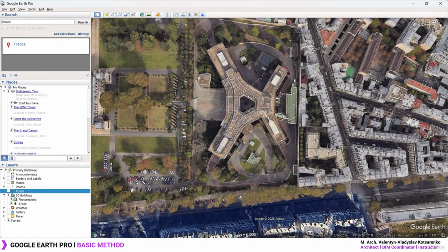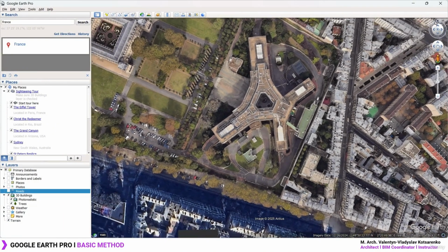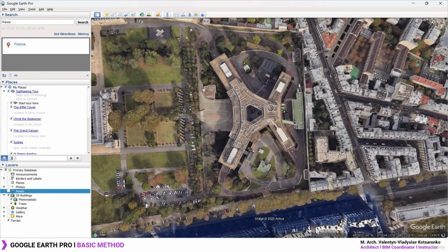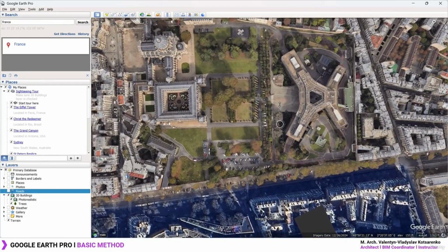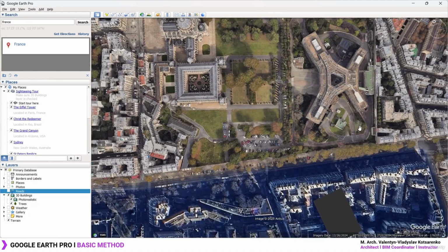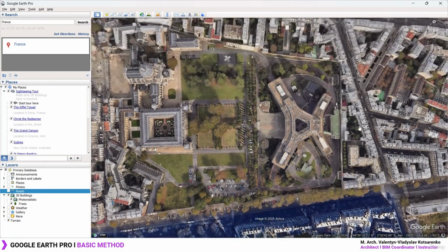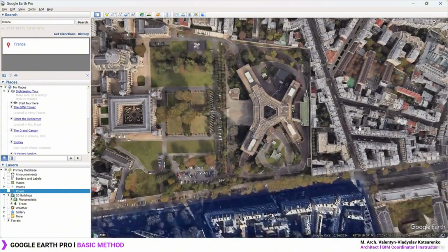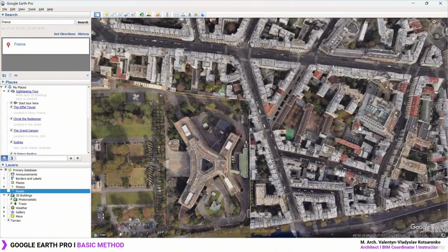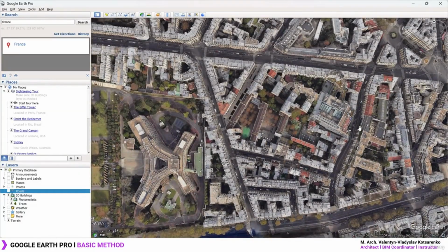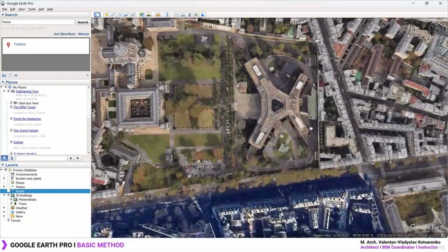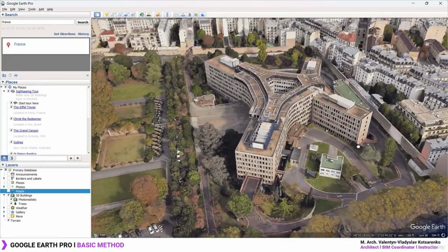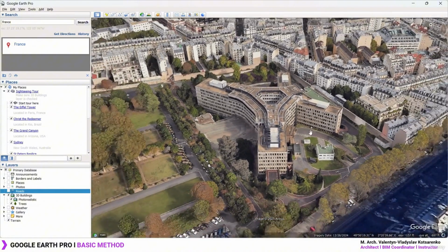Now you can do the fly-through with the drone in two different ways. Let's position the north over here just in case. Make sure you position the camera as perpendicular as possible, and what you can do is make a zigzag fly-through, something like this. Then you move to the right, down over here, right, up, right, down, right, up. This would be a series of movements, perfectly valid, and it will perfectly work once we input the results into Metashape.